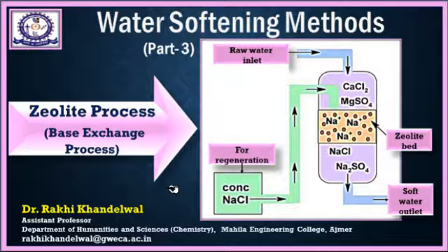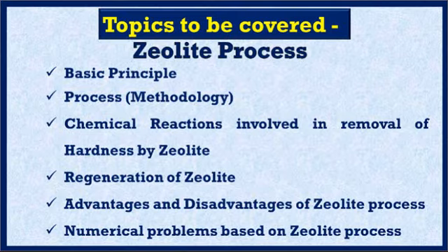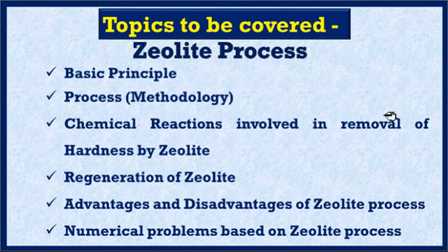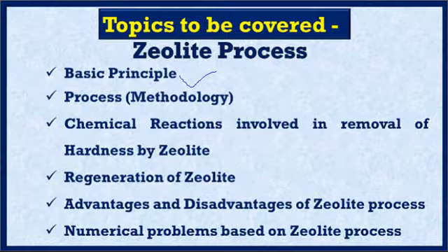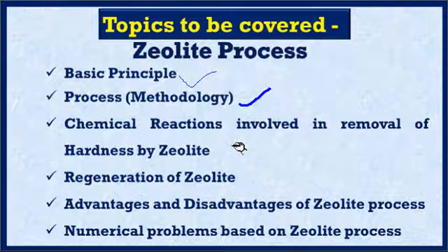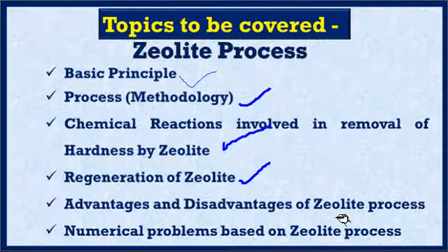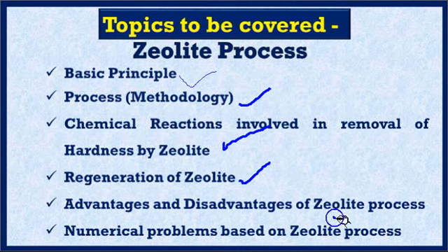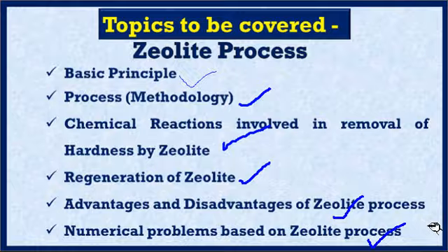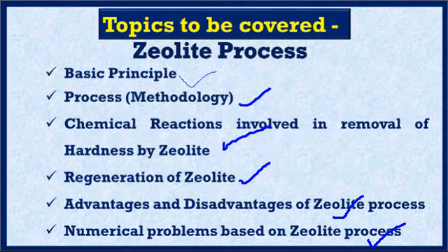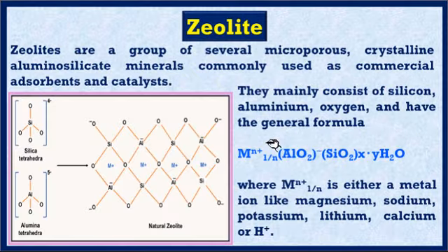In today's video, we will discuss the zeolite process in detail. The topics to be covered in today's video include the basic principle of zeolite process, methodology of zeolite process, the chemical reaction involved in removal of the hardness by zeolite, regeneration of zeolite, advantages and disadvantages of zeolite process, and the numerical problems based on the zeolite process. So let us begin with the basic principle involved.